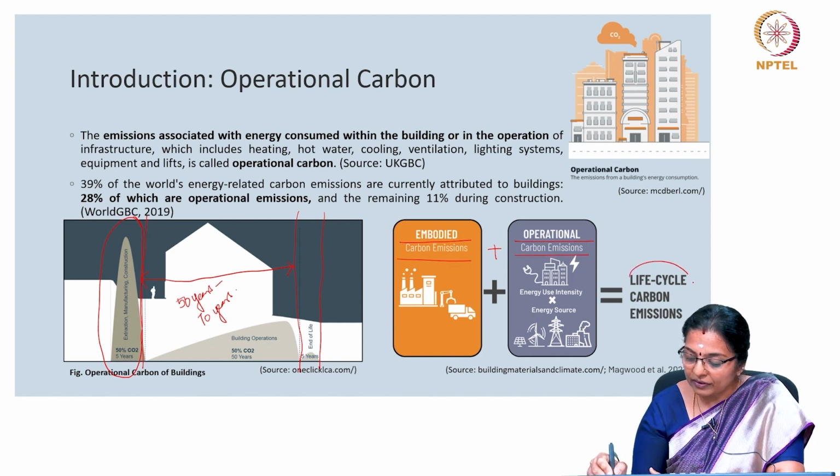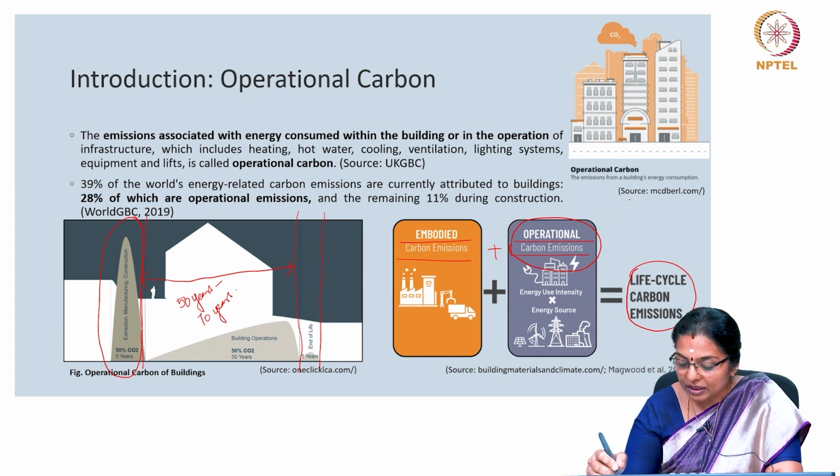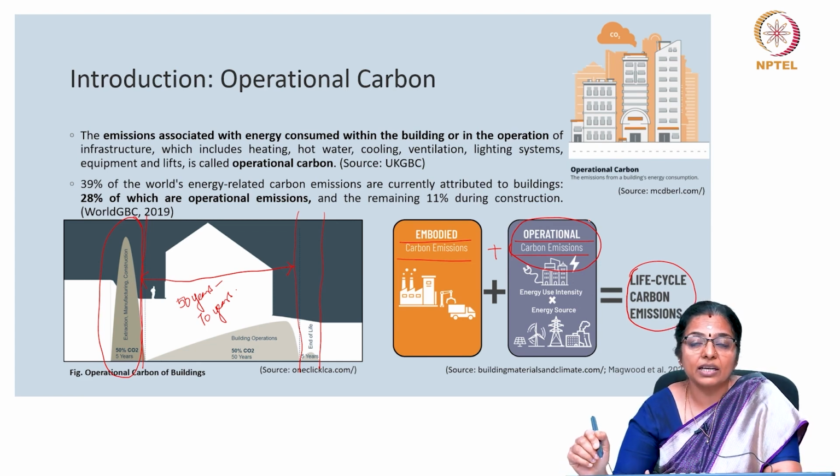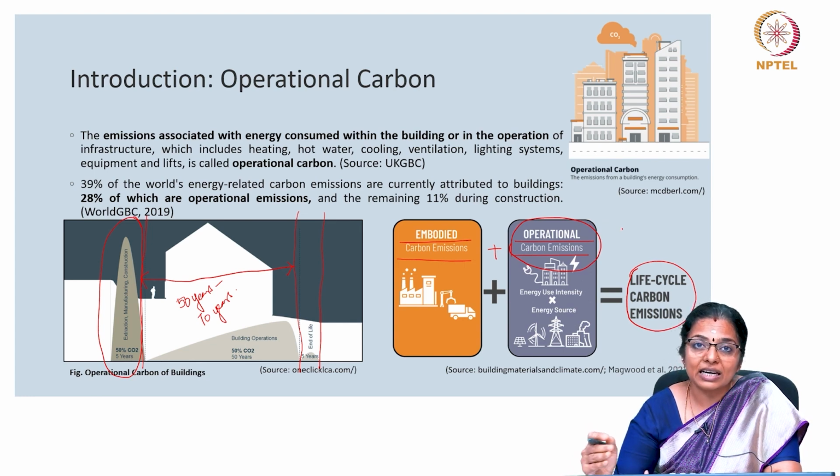Both together will form what is called life cycle carbon emissions. And operational carbon emission is dependent on how many years the building is consumed, along with all the contraptions that are used in the building which consume the energy. So, how much energy is the occupant consuming over a period of the building's lifetime.